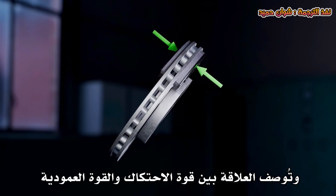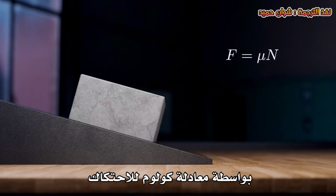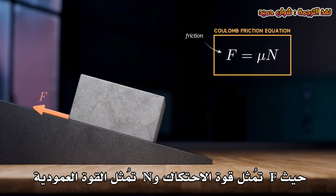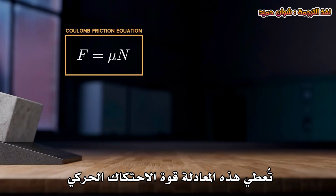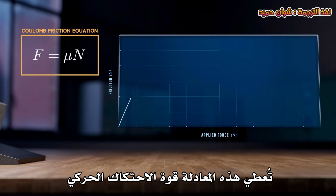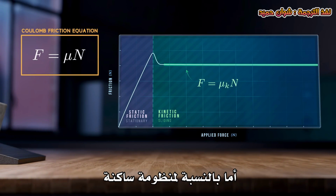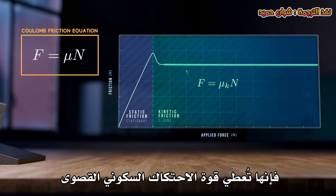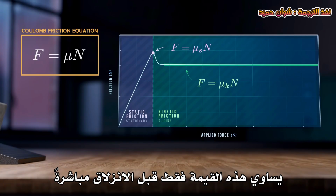The relationship between the friction force and the normal force is described by the Coulomb friction equation. F is the friction force, N is the normal force, and mu is the coefficient of friction. For a system in motion, this equation gives the kinetic friction force. For a static system, it gives the maximum static friction force. The actual static friction seen by the system is only equal to this value just before slipping.